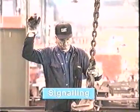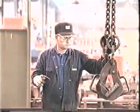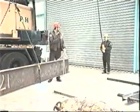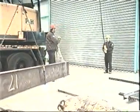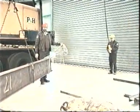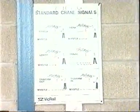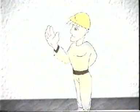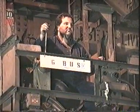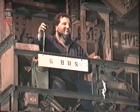There are standard hand and whistle signals which should be adopted at all times. As a general rule, only one hand should be used for signals, and only one designated person should give these signals at any one time. There should also be a card displaying these signals in your work area. Apart from the stop signal, operators should not respond to signals unless they are clearly understood. The operator should wait for a clear signal.